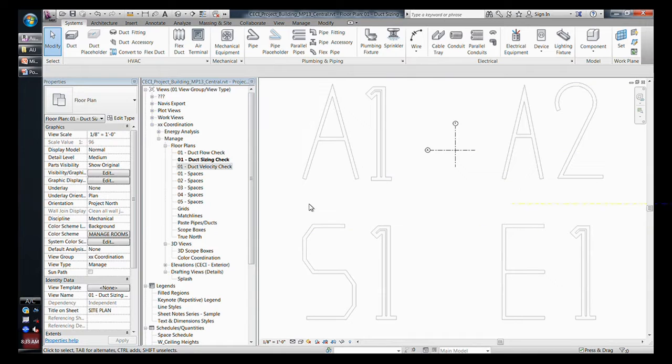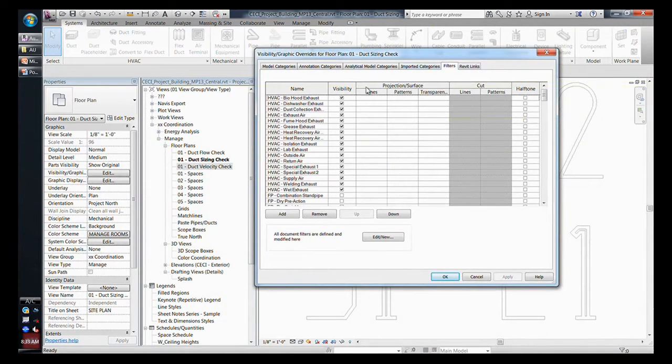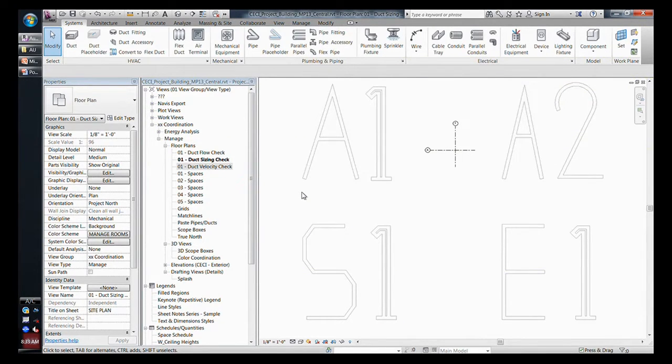To be honest with you, what I do here, and I'm hoping that I don't have any color overrides here, okay, and this is just a preference, is I'm using the latest feature in 2013, which is driving my colors through the system, not through filters. Typically, you can override the system with a filter or with this one. So the system coloring is rather low on the hierarchy, and you can override it with any others. So that's how I manage to display those colors.